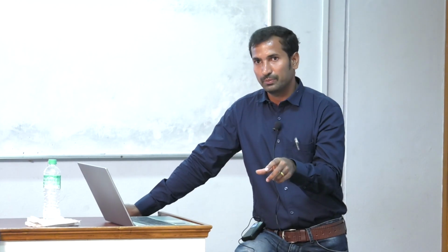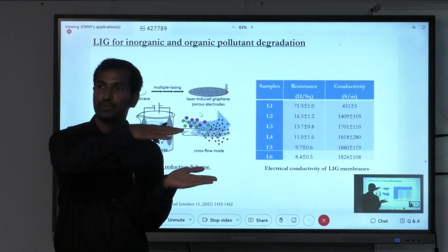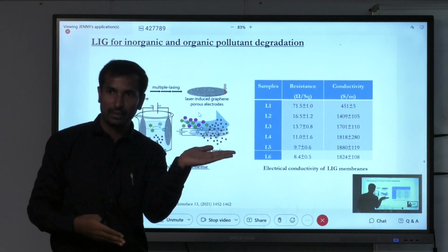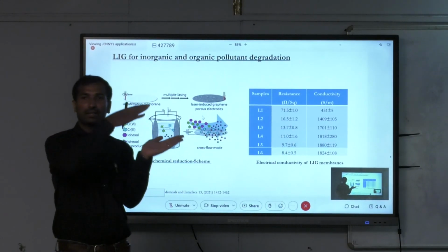We studied them together under the separation, the filtration process. We applied electricity here. Mostly what we did was apply a cathodic potential on our membranes, because our setup had inbuilt stainless steel electrodes. We used the stainless steel parallel electrode as an anode, then applied the negative potential to the LIG membrane.